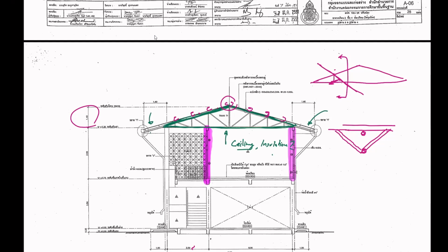So keep in mind that if you include the weight of the truss, no matter how small it is, it will create bending moment because it's a uniform load that doesn't act through the joint. So your truss will have local bending moment because of the self weight. But in typical design for a small roof system like this, we are safe to say that you can neglect the self weight for the time being.